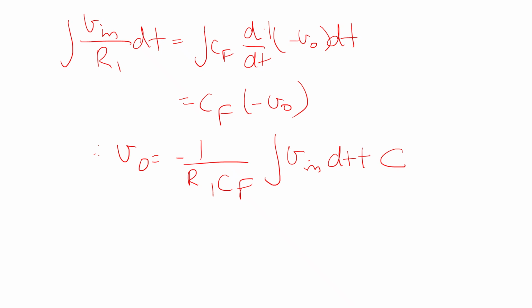When Vin is equal to 0, it will be working as an open loop amplifier. This is because a capacitor connected in the feedback loop acts as an open circuit. Then the capacitor reactance is equal to infinity. In other words, the input offset voltage Vio and the part of the input current charging capacitor CF will produce an error voltage at the output of the integrator. Therefore, in a practical integrator, in order to reduce the error voltage, a resistor RF is also connected across the feedback capacitor.